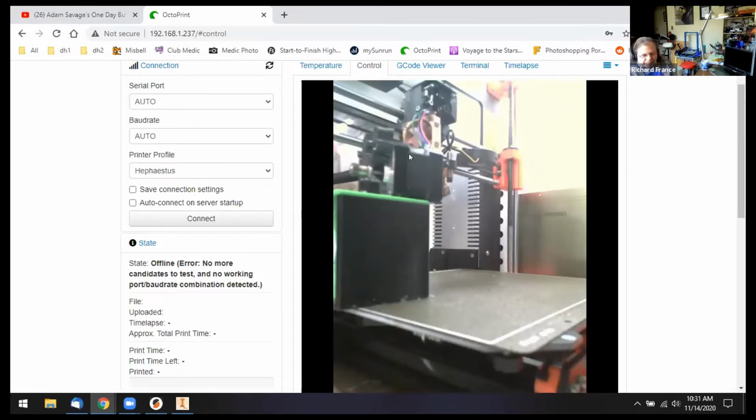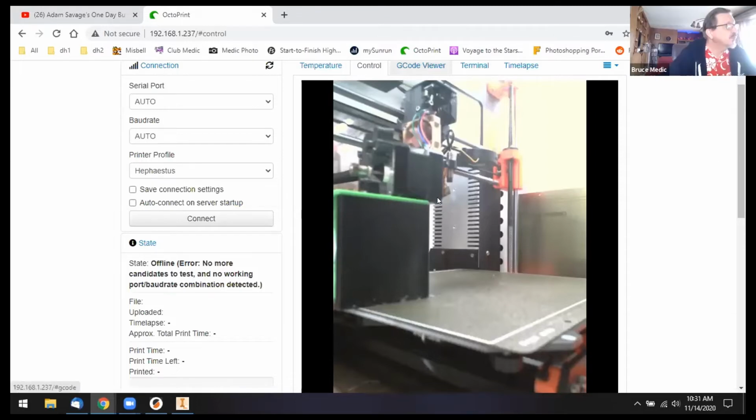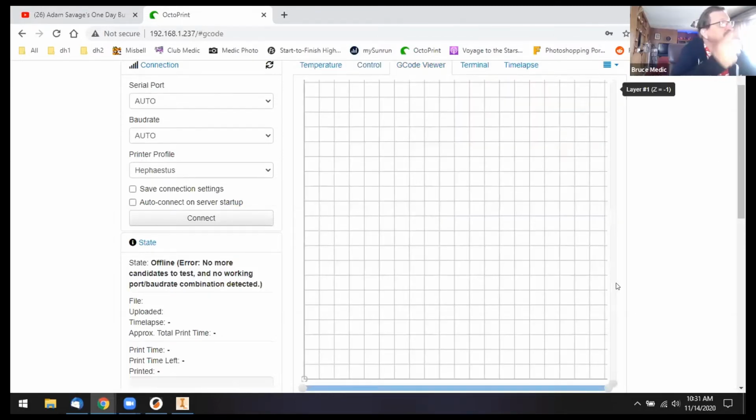So, and then if you wanted to see some of the other stuff, there's the G-code viewer up there. That tab actually shows you what's printing as it goes along. It shows you layer by layer. And there's a plugin in here that, say I was printing 6 parts on the bed, and one of them fails. It comes loose and starts sliding around. I can actually pause the print and tell it to quit printing that one thing. And then it says, okay, great, it quits printing that one thing, and then it continues printing the other 5. So maybe if I'm 5 hours into a print job and one thing fails, I don't lose 5 hours of print time. I just flick that one bad piece out of there, continue with the rest of them, and then reprint the single piece